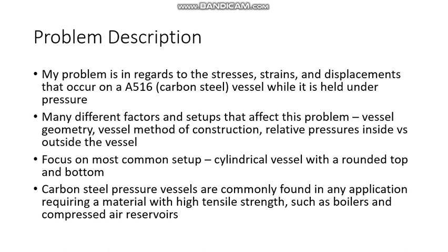Commonly for these problems you have a very large pressure inside the vessel and it is ambient pressure outside, but it is possible, and it occurs, when there is a relative pressure outside of the vessel as well. For most of my project I will focus on the most common setup, which is a cylindrical vessel with a rounded top and bottom, so a pill-shaped vessel, and we can look at either the end caps being bolted on or welded, as stated earlier.